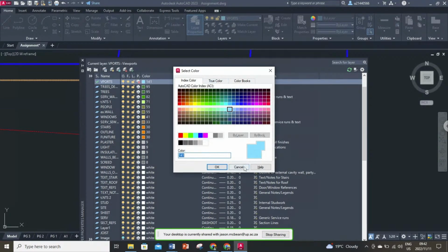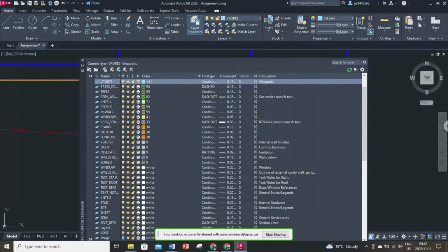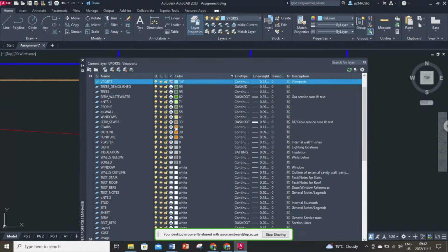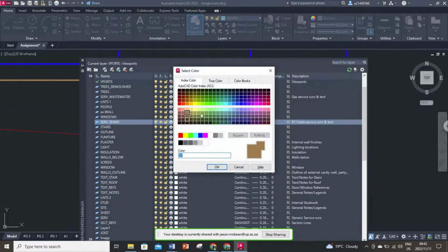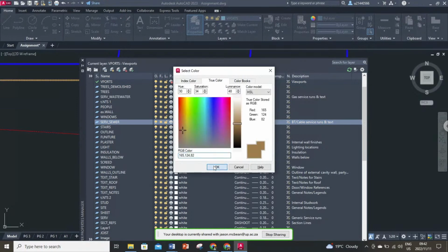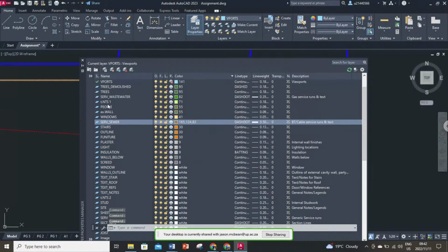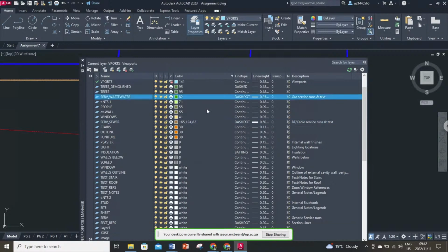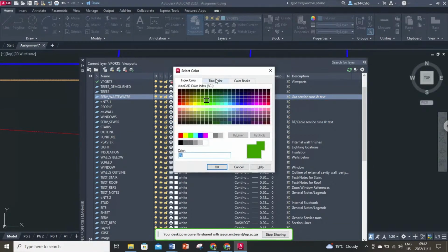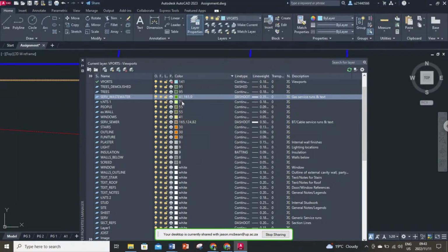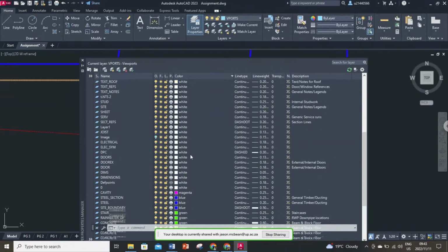As soon as you change those colors, let's just look at your services quickly, just fix that quickly. So let's go to service waste. It's very easy to fix these. True color, press OK. Now you see it's got a true color. Maybe services wastewater, and let's just sort that out quickly. This is the only thing. Next year my template will be upgraded with the true colors. So going forward, I will fix this just because I think it's going to be way easier.